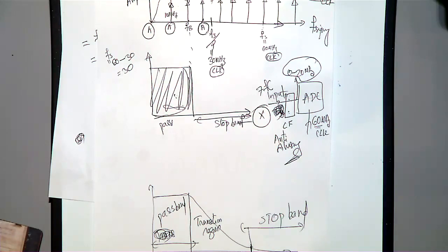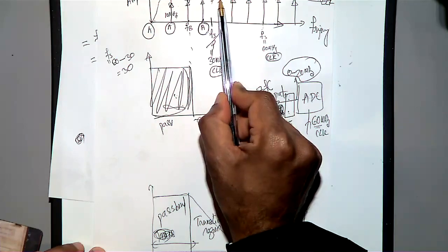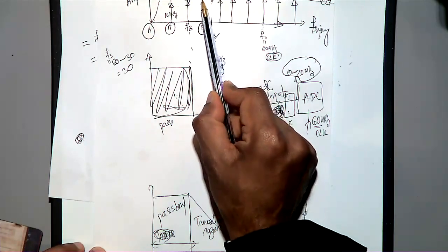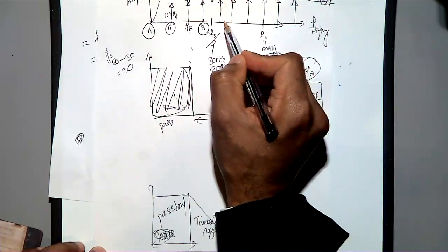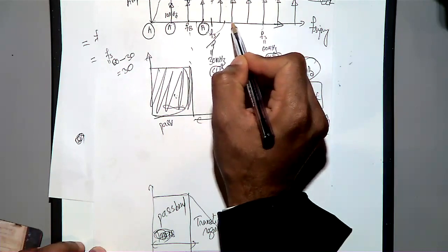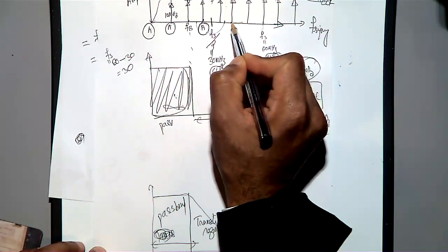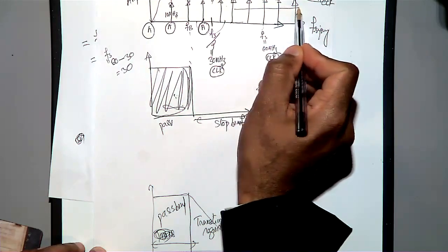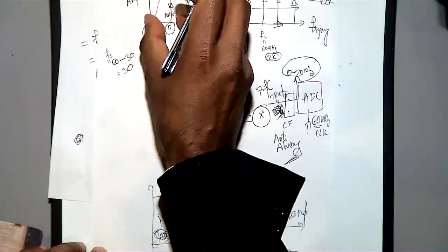Yeah, so if you take 40, because here you got 30. 30 is sampled wrongly, but 30 will appear in 30. If you got even a 35, where 35 will come? 35 will come again here. You know what I meant? If anything is there above 40 will come definitely. So above 40, whatever is coming, all these things are coming to this region.